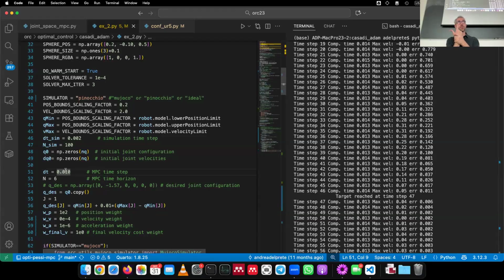And then there is a second point. Less reactive to trajectory changes. If I change the trajectory. Yeah, if you still use the time step as your control period, of course, that's going to make your controller slower, because you're recomputing the control actions every 20 milliseconds instead of every 10 milliseconds. But that's also an advantage, because it means that you have 20 milliseconds of computational budget to do the computation, so you have more time to compute stuff.